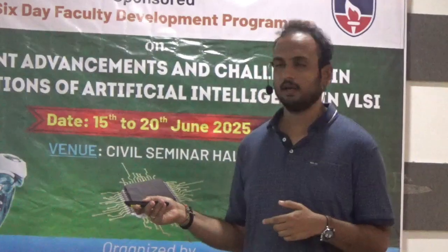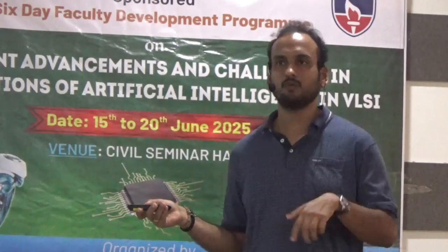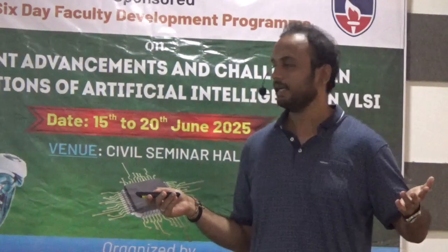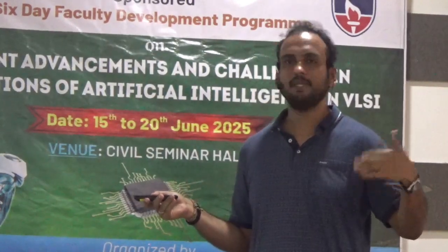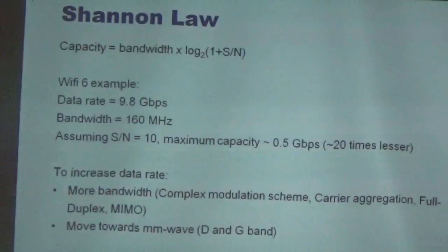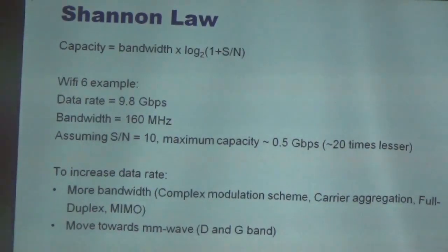And then it is always better to move towards the higher frequency range. When we move towards higher frequency, like D band or G band, these are the millimeter waves, more than 30 gigahertz. When you go for a higher band, higher frequency, you can get more bandwidth. There are other challenges which will come with that.